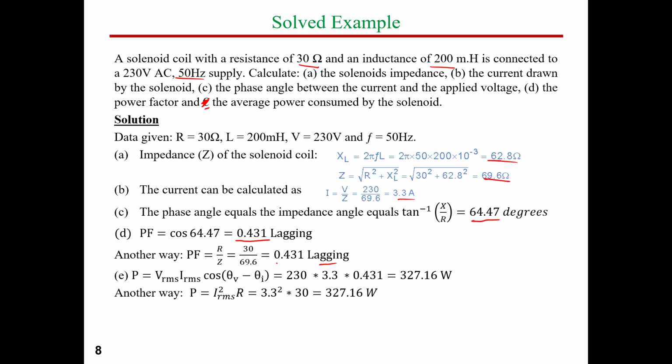By the way, guys, for any problem, if we ask to find the power factor, you have to identify the type of the power factor. If you said only 0.431, this is half of the answer. This is not the full answer. The full answer is the power factor magnitude and type, except only if it is 1, because 1 is unity. Or 0, sorry, even 0 you have to mention lag or lead. So the only exception is for unity power factor.